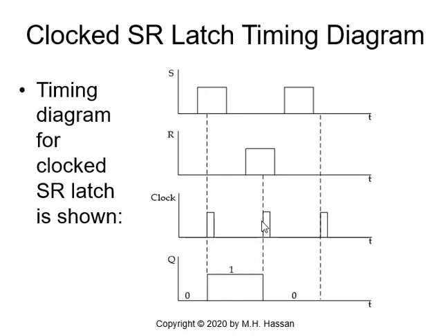At the next clock pulse, we see actually that R is 1, but S is 0. So the Q will reset to 0. And at the next clock pulse, we see no inputs. Both are zeros, and it will remain 0 because it is 0.